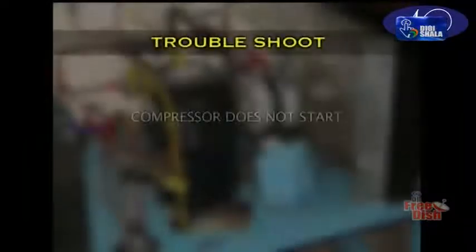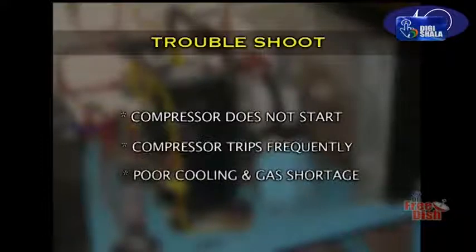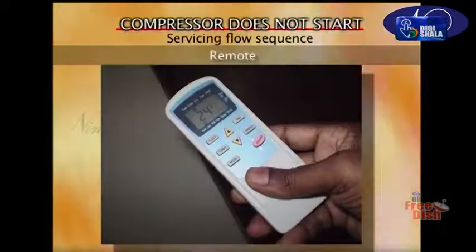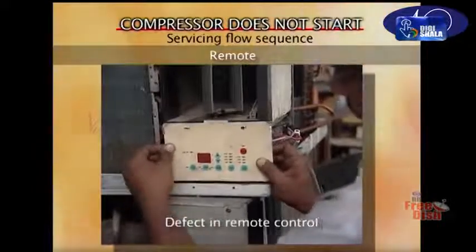Troubleshoot: compressor does not start, compressor trips frequently, poor cooling and gas shortage. Servicing flow sequence for compressor does not start. Check the remote control. There may be a defect in the remote control.